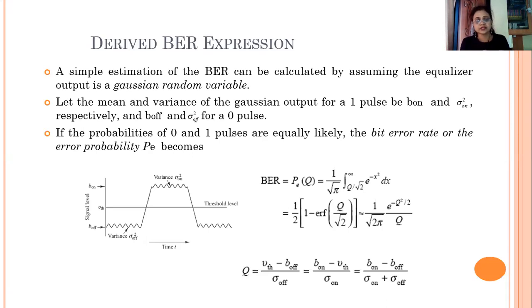So this is how, student, if noises will be less, obviously the variance and the mean value will be less affected, and the quality will improve for more number of bits, and there will be less chances of the decision circuit to give erroneous bits. So this is the way you have to link the expression of bit error rate via quality factor through these parameters to the bit 0 and bit 1 and the noise added into it.